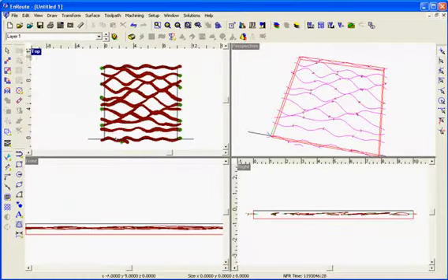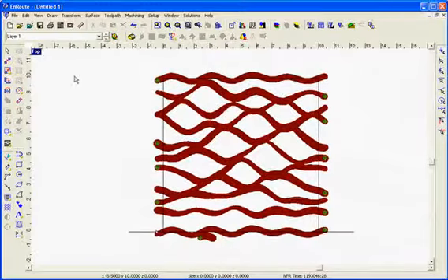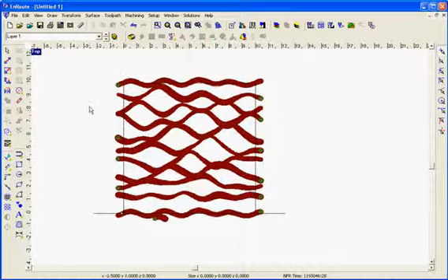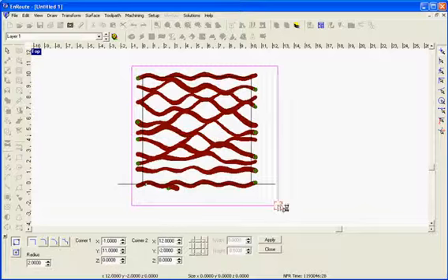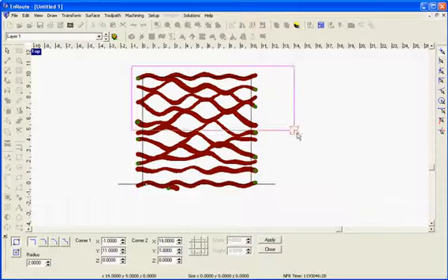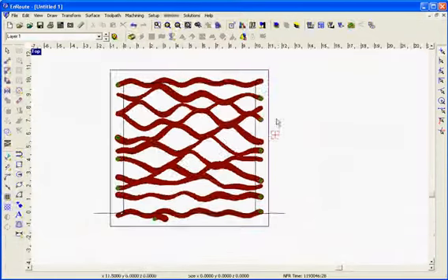Now let's see if these parts fit up correctly, and an easy way to do that is to do a 3D simulation and save your simulated part as a relief and see if they match on all sides. Because the only toolpaths that simulate are the ones within the material being simulated, I'm going to use my rectangle tool and draw a little bit bigger shape around my plate.